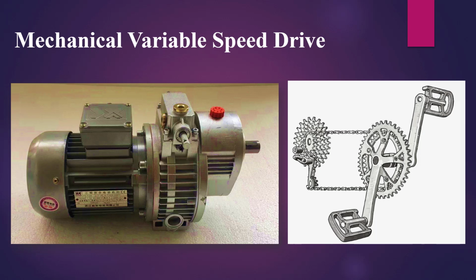The basic concept behind adjustable sheave drives is very similar to the gear-changing arrangement used on many modern bicycles. The speed is varied by adjusting the ratio of the diameter of the drive pulley to the driven pulley. Historically, electrical VSDs, even DC drives, were complex and expensive and were only used for the most important or difficult applications. So mechanical devices were developed for insertion between a fixed-speed electric drive motor and the shaft of the driven machine.